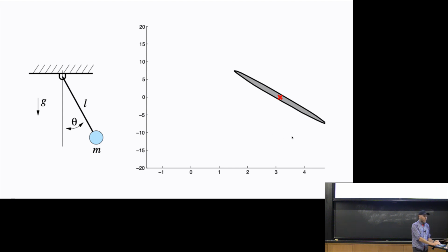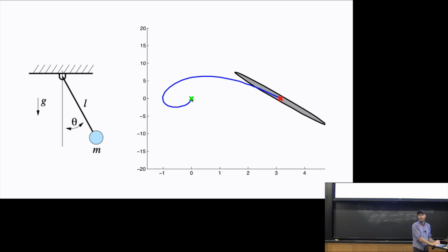I'll have an equal probability of picking anything in the white region and 0 probability of picking something in the gray region. Okay, so I pick a random sample. I picked one here. I'll do trajectory optimization to try to get this back to one of the other parts of my tree. That's exactly like the RRT, but because, like we said, the extend operation for dynamic systems is hard, we're going to use full-on trajectory optimization to do it in this case.